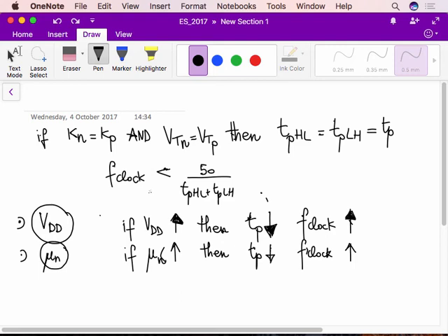And so we have this tensile strain applied to the n-MOSFET in order to improve the mobility of electrons. And then we have this compressive strain applied to silicon in the p-MOSFETs in order to improve the mobility of holes. Okay? This is really trying to change the type of materials, the properties of materials, in order to improve the mobility and then the device performance.